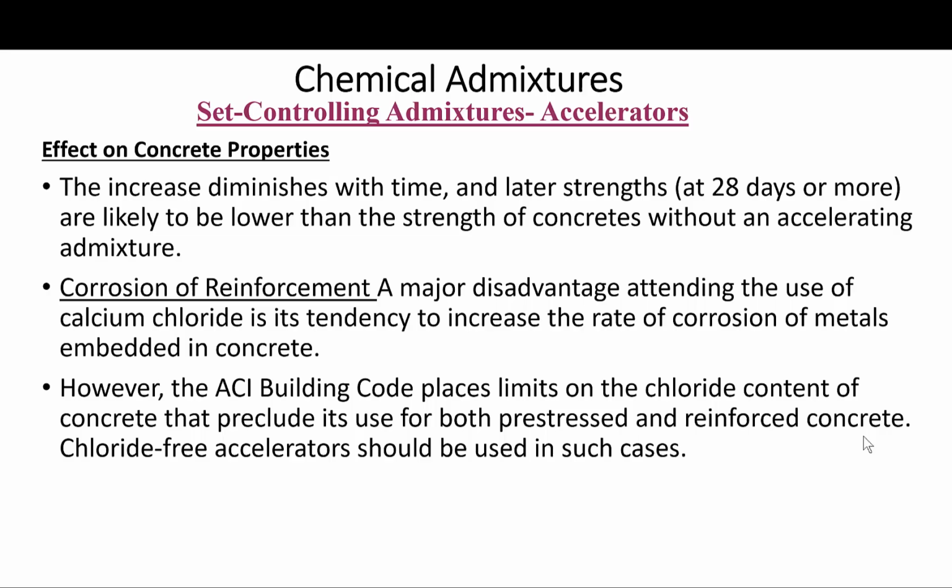Also, tests have shown that the use of calcium chloride in concrete reduces its resistance to sulfate attack and also aggravates the alkali aggregate reaction. If these are potential problems in your job, calcium chloride, aside from the corrosion issue, should probably be looked at carefully. The quick-setting admixtures can be expected to reduce the durability of the concrete or mortar if they have an adverse effect on strength. Okay, so ultimate long-term strength should be verified.